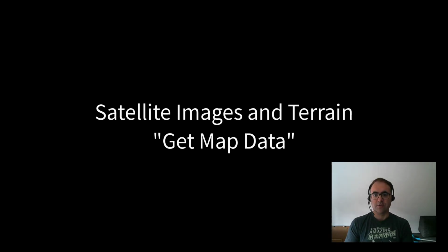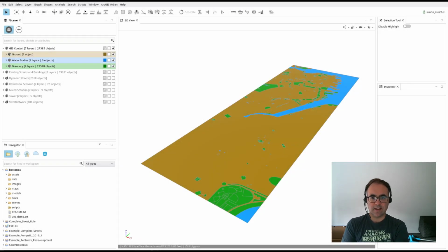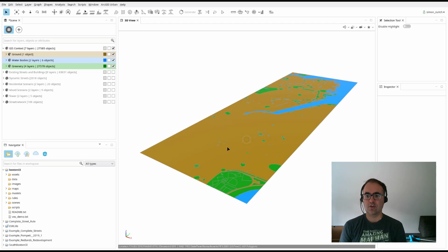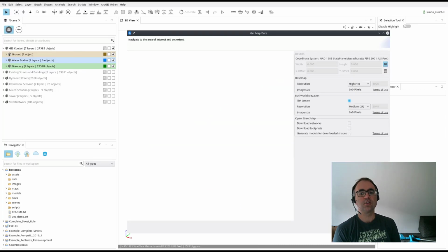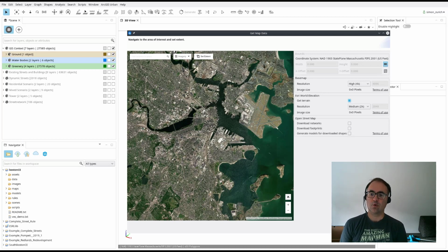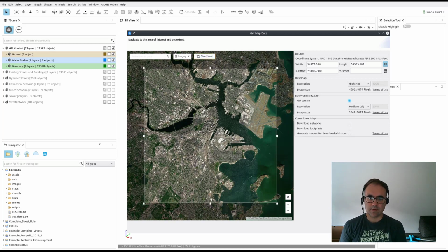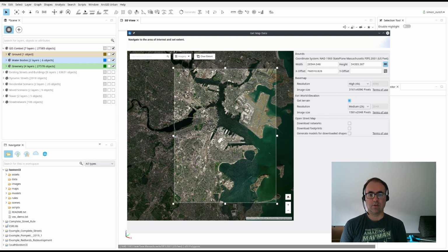There are many approaches to set up a city layout with CityEngine. In this case, we will use satellite imagery to trace some streets around Dorchester Avenue in Boston and use the resulting parcels to apply our building designs written in CityEngine's procedural language CGA. For this, CityEngine provides a handy feature called Get Map Data. It will take the current location of the scene on the world and query an Esri cloud service which will provide elevation and satellite images.